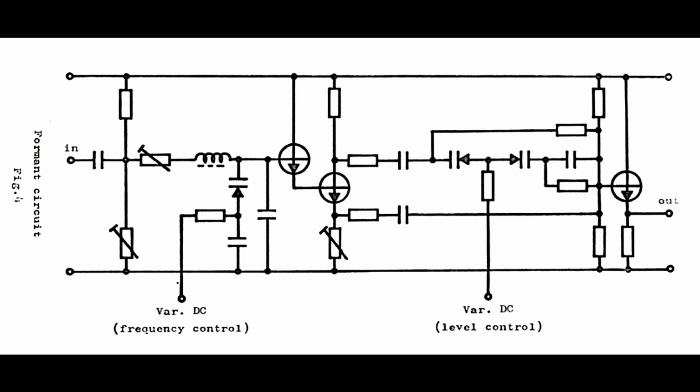They got a very low impedance driver with an output impedance of only 4.7 ohms. And this drives the entire Formant filter section. And in series with each input here, there is a potentiometer on the front of the unit, and this goes to the in on this schematic. So of course the relationship between those trimmers here sets how aggressive is the input volume pot, and how much is then going on to the rest of this filter.